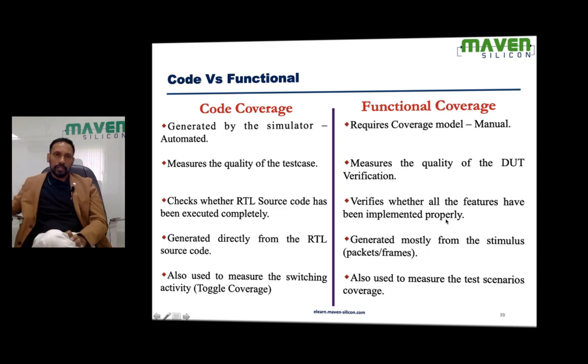And code coverage is generated directly from the RTL source code. You have written the RTL, there is a test bench. While running simulation, you apply code coverage. The simulator is going to generate code coverage directly from the RTL source code. We don't generally apply code coverage for the test bench.